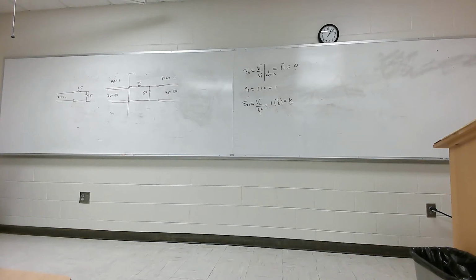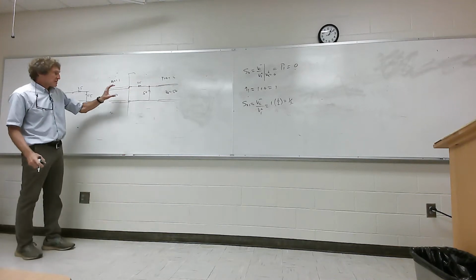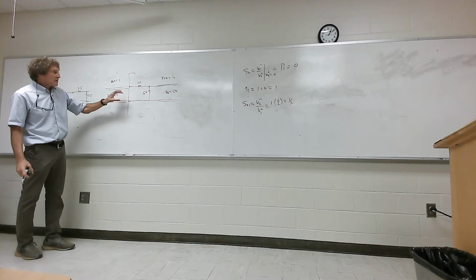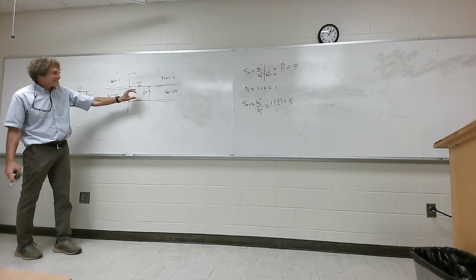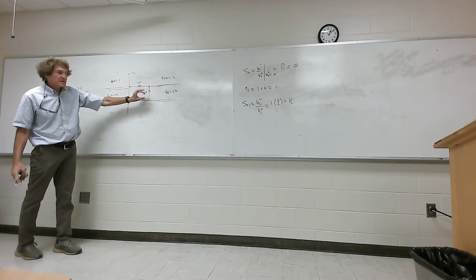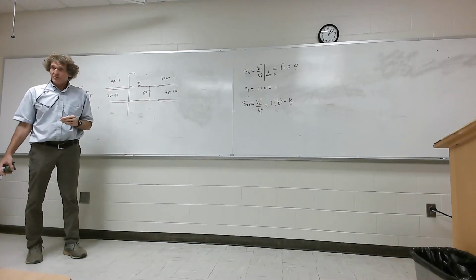When I take a look at that V2 minus over V1 plus, it's how much gets out that port compared to what comes in. Here, how much comes in here? Well, that's V1 plus. Of that value that comes in, because the transmission coefficient is 1, exactly 1/2 of it's developed here, because that's 50 in parallel with 50. So it's a half. Y'all follow me?